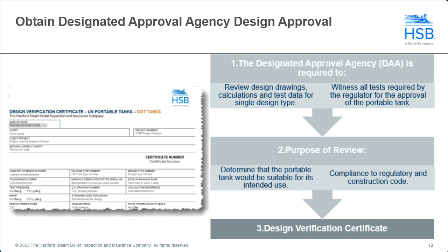What I mean by all tests is, for example, the container. If the container is the size where the Convention for Safe Containers, CSC, is applicable, the manufacturer has to build a prototype, and that prototype has to be tested. If it's going to be stacked or lifted, it has to go through a lift test, a stack test, and then you also have what they call a longitudinal impact test. I don't know if you can picture the crash dummies in the car, right?